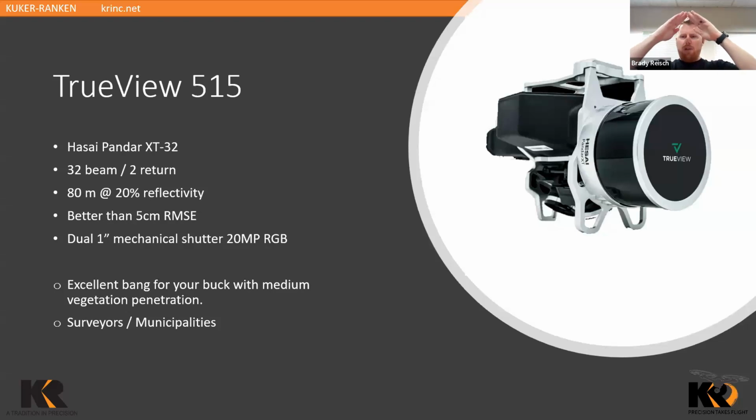Our area that we're scanning is wider, and if you have a single image, it shrinks that beam down, which means on the sides we have a lot of black uncovered area, where we're not colorizing that point cloud. So there's two cameras on here in order to bring that width back out to have full coverage of where the LiDAR or the optimal LiDAR scanning is located as it touches the ground.